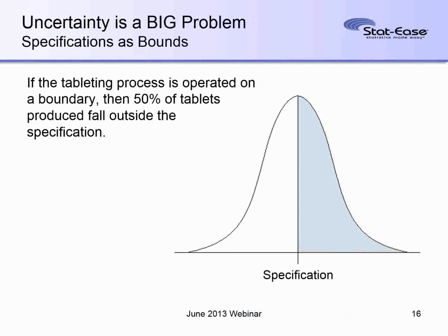Now, one of the issues with modeling with statistics and DOEs is the prediction you get is the predicted mean average outcome at certain settings of your process factors. If you operate on the edge, that literally means half of your outcomes will be in spec and half will be out. I don't know of anybody who can operate that way successfully.